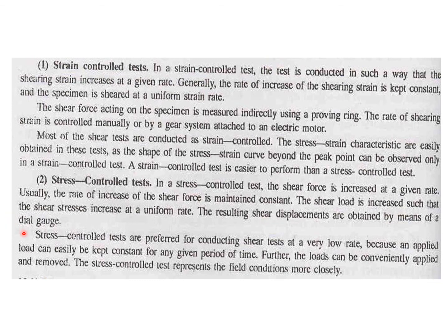Stress control tests are preferred for conducting shear tests at a very low rate because an applied load can easily be kept constant for any given period of time. Further, the load can be conveniently applied and removed. The stress control test represents the field conditions more closely.